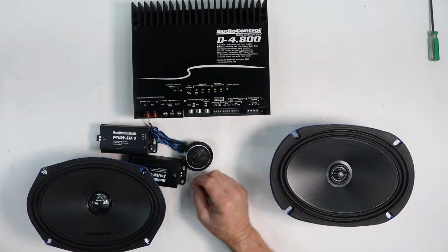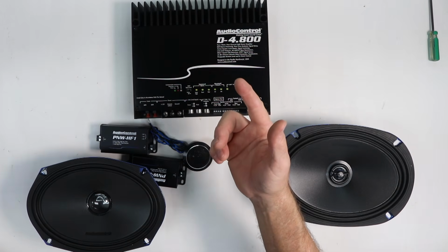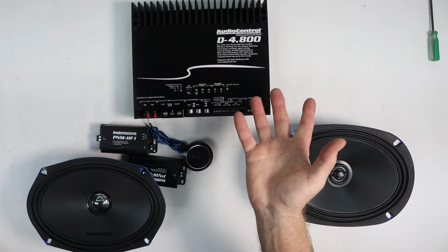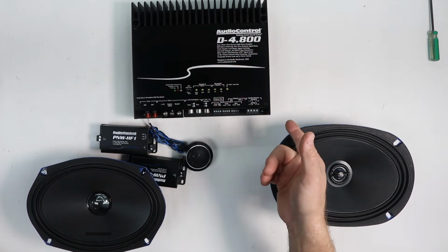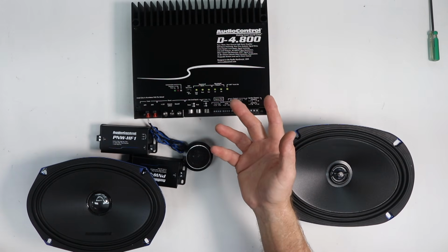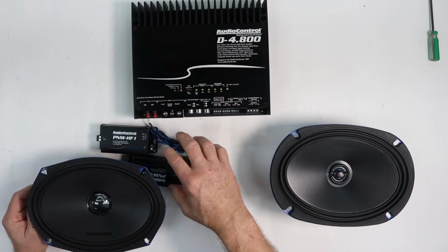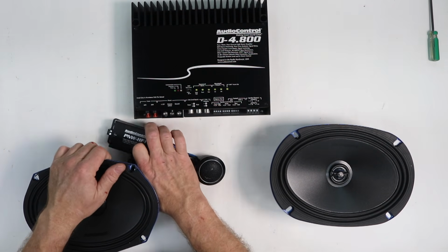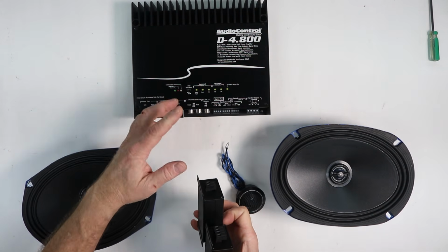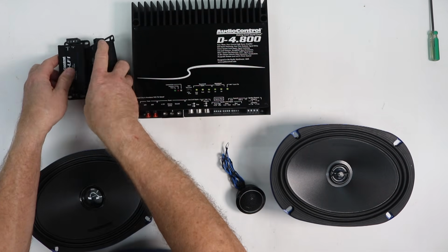But I bought a 4-channel amplifier because in my mind, I was thinking front, rear, sub, right? Not front tweeter, front mid, rear speaker, sub. Oh, it's a few more channels. It's 2 more channels that I didn't think about. So now I'm going to do my passive active. I'm gonna set this for 80 Hertz high pass. I'm gonna put these 2 in the car.